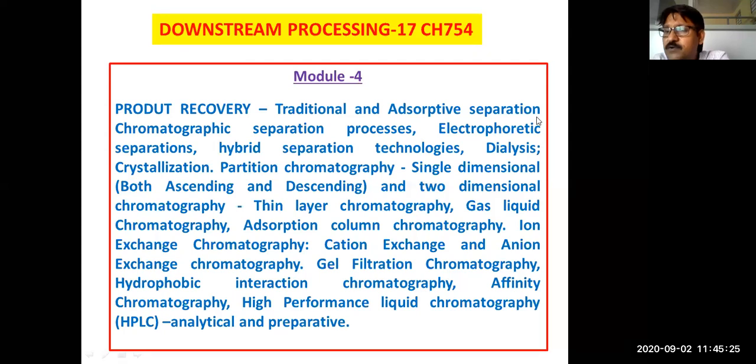Here what we are discussing in purification is restricted to the sorption process. In sorption, the interaction between the solid phase and the liquid phase is exploited to separate the component. So therefore we are going to exploit the phase or understand the phase. Usually this will be by van der Waals interaction. Van der Waals means physical interaction, after which you can remove it easily. Sometimes it will be polar forces, sometimes it is ionic, or it will be affinity.